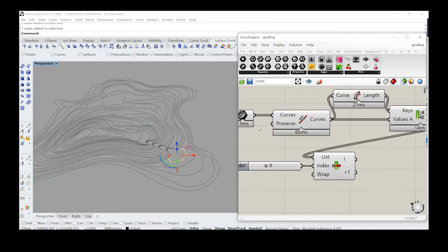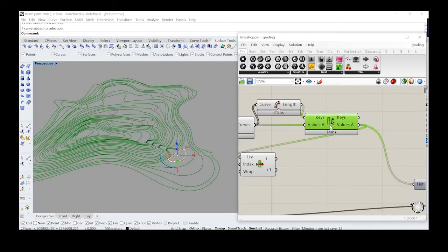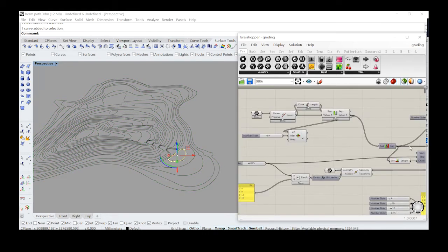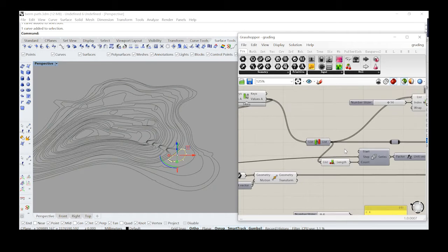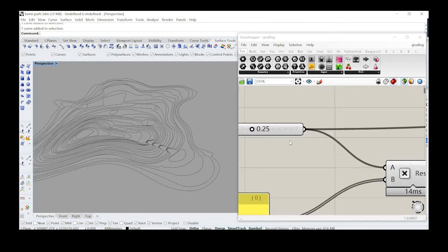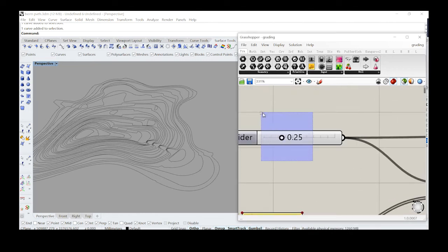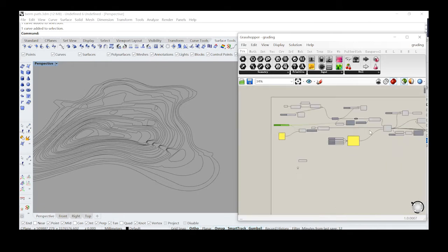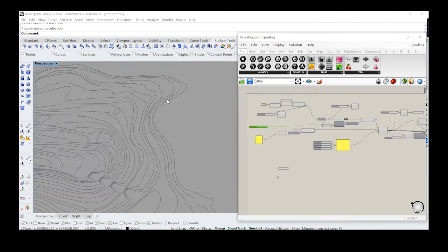And note that I'll leave out these platform areas first because we want to put them back in with all the other contours after we move out the contours in the right order at the right elevation. So after we put all the contours at their correct elevations, we can use insert list to make the complete list of contours.